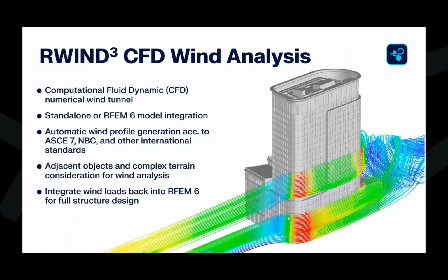Now, RWIND can certainly be used as a standalone. We have architects, for example, taking advantage of this. It's not necessarily just for the structural engineer where you could import in an IFC file, because all that we need is the geometry here to determine what these wind pressures are. But the powerful thing is integrating, of course, with RFEM 6. So we can automatically send our structure from RFEM 6 into RWIND, calculate the wind pressures, and then bring the wind pressure information back into RFEM 6.